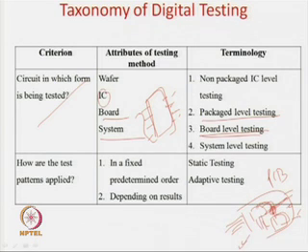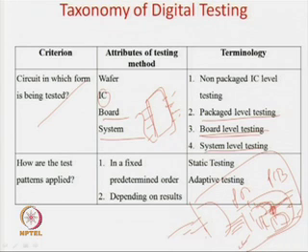All input outputs of the IC you cannot get it. Now, if I go for a system which is called the system level testing, testing somewhat becomes more difficult because now all the PCBs are connected in a system and you can have access to only the input output of the whole system. This is the system, there are many PCBs, in the PCBs there are many ICs, but you can only access the input output of the PCB, internally you cannot access.